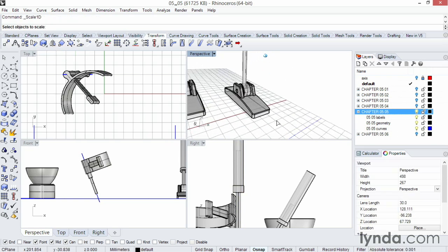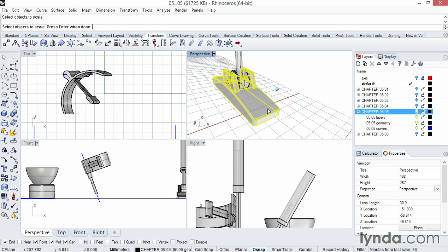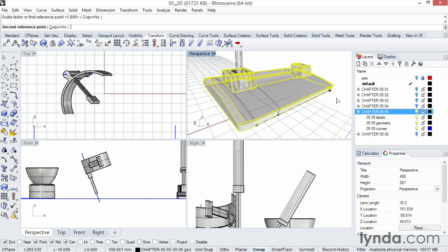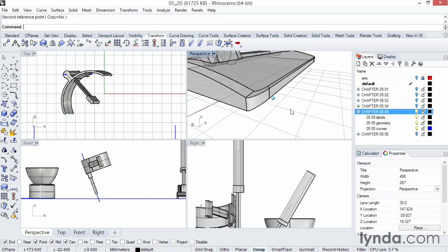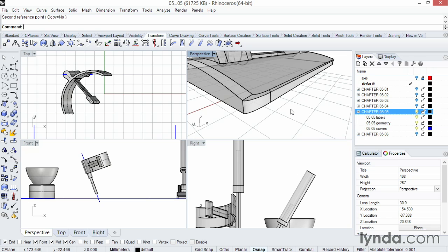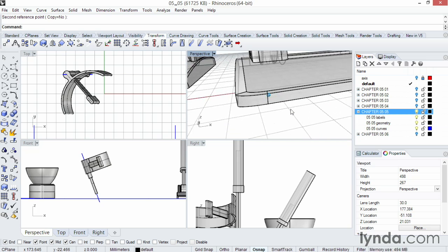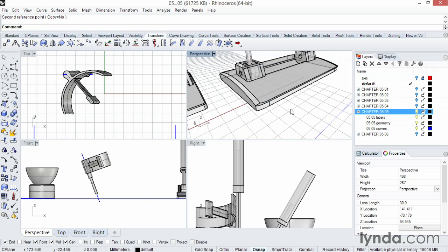I am going to scale the foot here, and we'll see this problem I mentioned as far as messing up the fillets. So I'm going to stretch that guy way out. So just a word of caution, if you're going to be scaling stuff without being in 3 dimensions, you might want to save all the fillets for later, not have them already done like I am now, because you can see those are just kind of smeared. And it's probably not what you want.